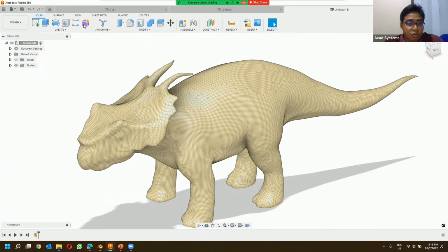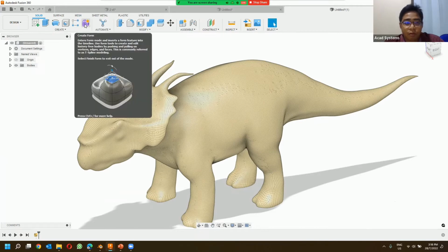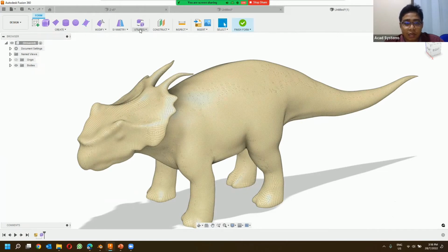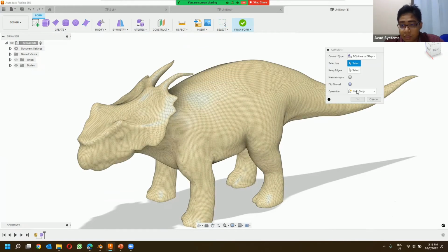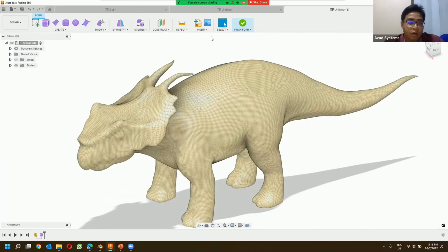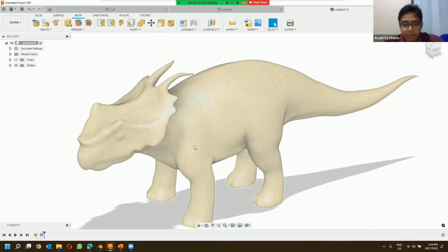If you want to use freeform modeling, T-spline, it allows you to directly edit and convert this quad mesh into a T-spline. So I can use convert, choose quad mesh, and then select this one and convert. But let's say I don't want that, I can just go ahead, and from the mesh itself, I have too many faces over here.